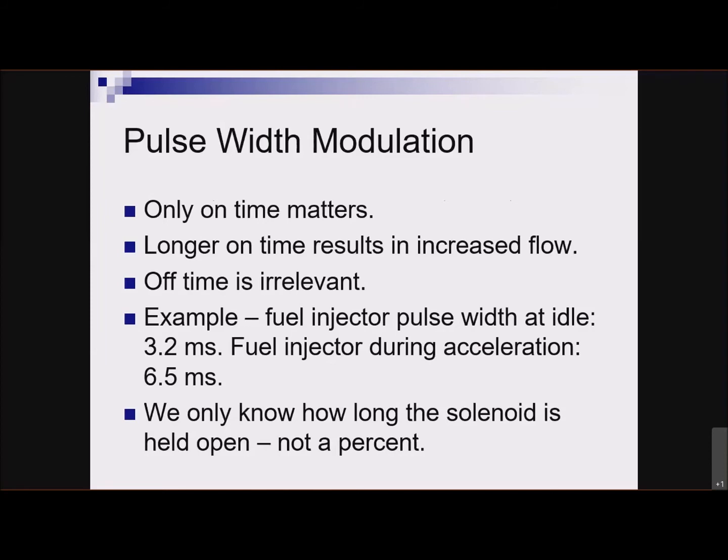Years ago, the only thing that I knew of that was pulse width modulated was fuel injectors. And that's why I use this as an example, right? But they've started to use it. And when I say they've started to, I mean, this has been going on for years now. To control current flow through things such as headlights, pressure control solenoids, again, in an automatic transmission.